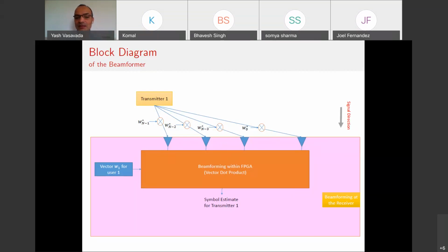If the angle of arrival changes, the only thing that changes is the argument of the complex exponential. Everything else remains the same. So the signature is the DOA or the AOA, the angle of arrival theta that we have defined earlier. The reason I wanted to bring it out is because just like this is called the spatial signature vector, we have also seen signature sequences, which we have called the spreading sequences in the context of CDMA.